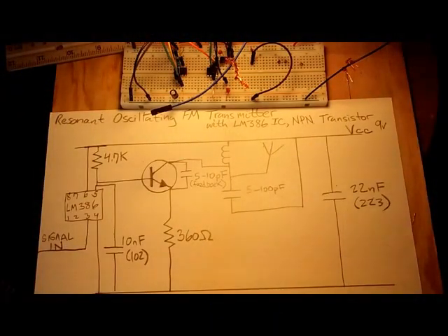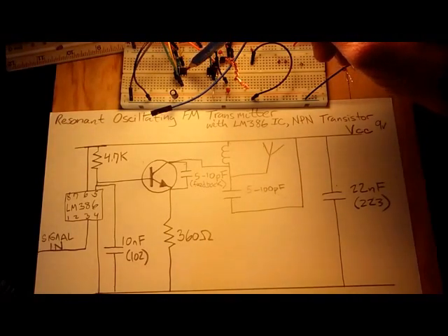Guys, welcome. Let's calculate the inductance and resonant frequency of our homemade FM radio transmitter, and then check out how a square wave produces harmonics in multiples of the original transmitted frequency. So here's our transmitter, and you can hear the tone that we're transmitting today coming off this 555 timer chip